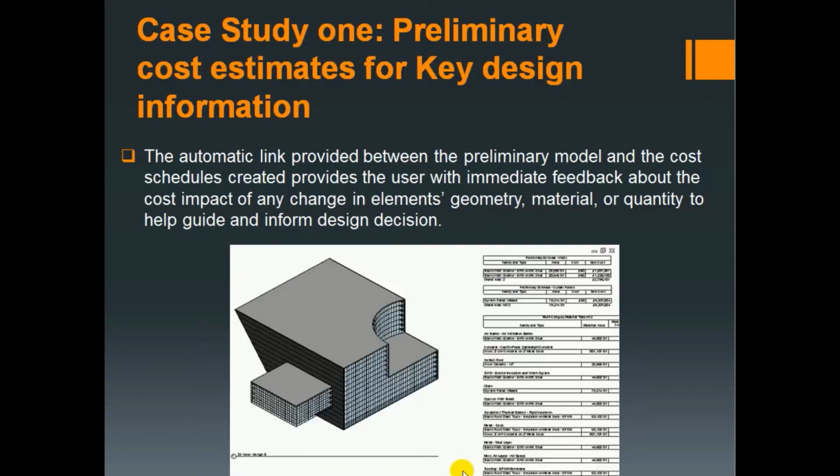Revit has the power to develop a cost schedule based on inserted rough costs per unit of each key element in the building. On the right of this figure is a cost summary of the preliminary design shown on the left side. Revit allows the modification of this model, like adding a floor, expanding the building, changing the type of the materials, and automatically updates the cost summary. This powerful tool plays a major role in providing cost feedback in early stages for alternative designs.